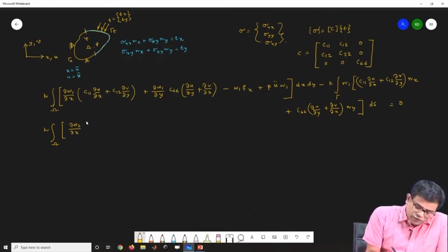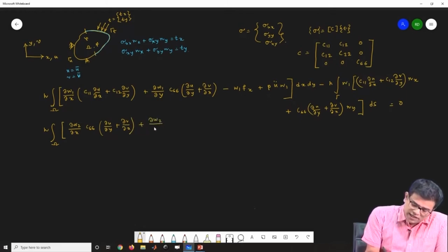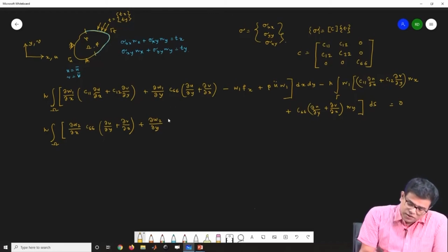Then you will have del w2 by del x times c66 del u del y plus del v del x, plus del w2 by del y. Then you will have the second stress term, that is sigma yy, so c12 del u del x plus c22 del v del y.